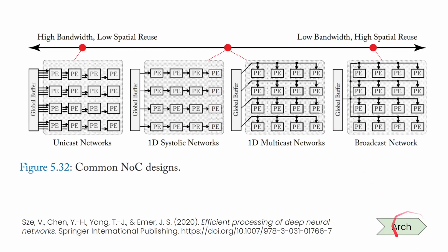Next, let's talk about the architectural level. The architectural level in a computer chip, we're talking about microarchitecture. I describe microarchitecture as: what do we put on the chip and how do we connect things together? So in this first diagram, we're going to look at how things are being connected together. Literally, how do we wire together the different processing elements? That's what PE stands for, processing element. And that's where we perform those multiplications and additions we need for matrix-matrix multiplications.